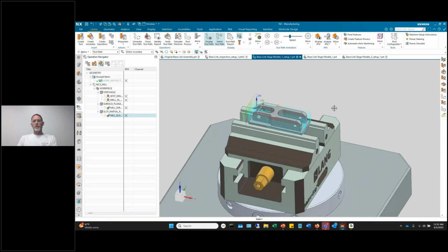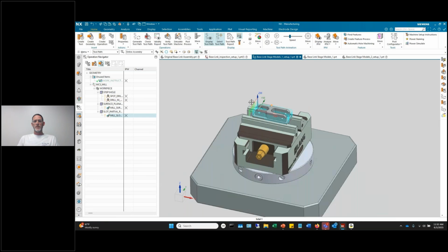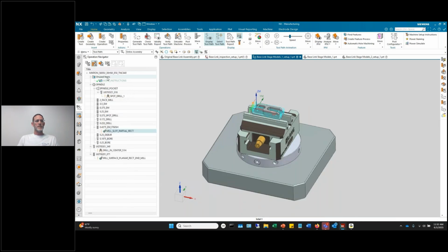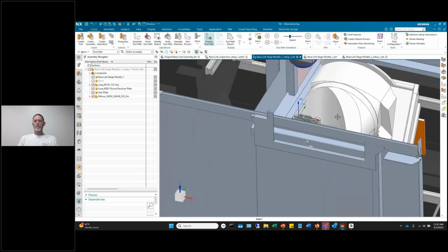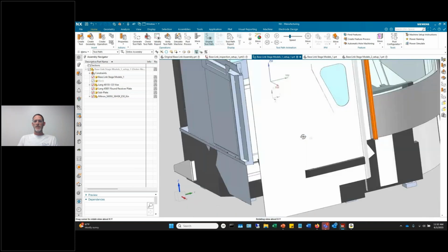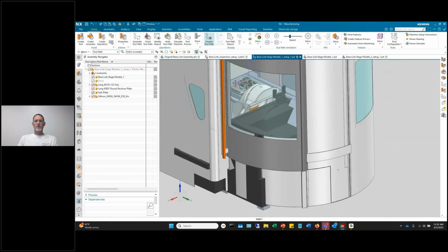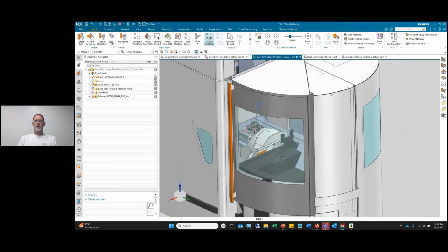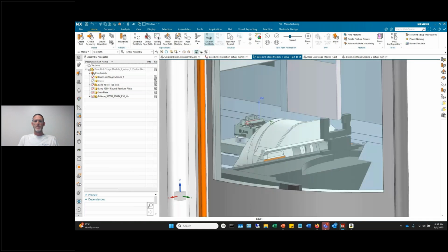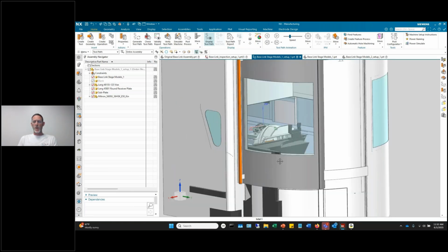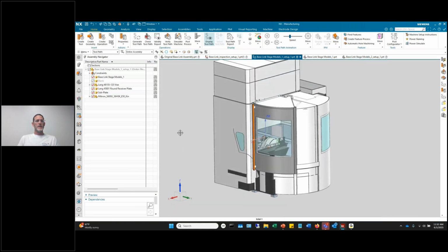So this is running through our digital thread. Now we have this done. Now what happens with our machine tool? We would reach out to a library. We would say this is the machine that it has to go on. But all of this is unmanaged. So what happens if I changed up the post processor to do something I like? Or what if this guy did something and destroyed his post processor and now it's not accurate? This is a big problem with an unmanaged system.